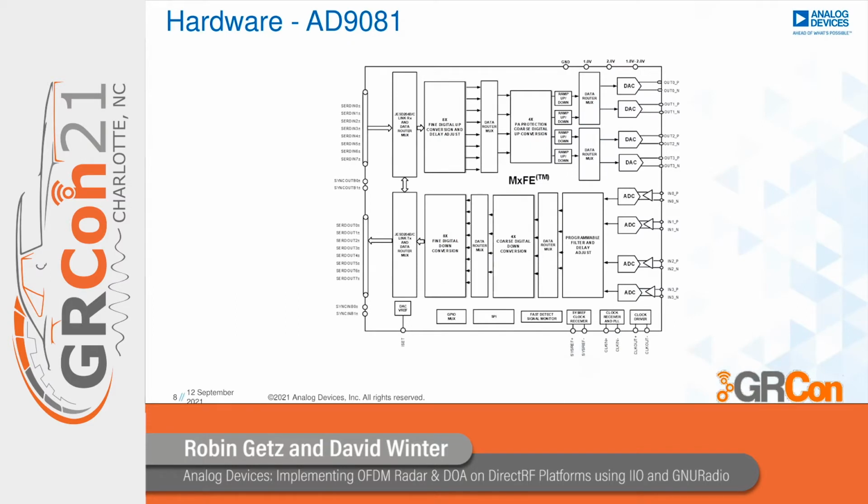Now, just a quick primer on how you use DirectRF systems, because 12 gigasample per second is obviously a bit much to handle in an FPGA, at least if you don't want to go crazy. So there are lots of down conversion, up conversion, interpolation, and decimation hardware filters available for you.